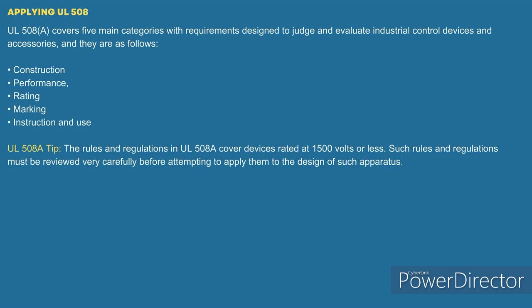But it's 110.26(A), Andrew. I'm not exactly sure of the whole exact part of where you would go, but 110.26(A) is where it starts, and you would just follow it through. But I will say this: if you have somebody that's coming in behind you, and it's not a facility that already has set up safety procedures and everything, I'd say you need the clearance, because you don't know what somebody else is going to come in behind you and do. Yeah, you don't want a guy to come in and try to test it. Somebody doesn't know what he's doing.